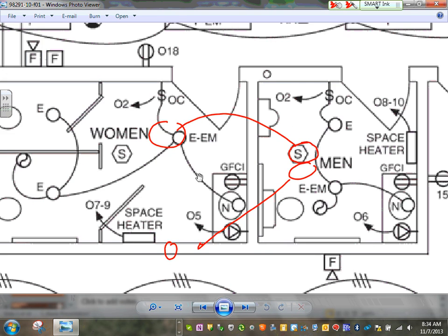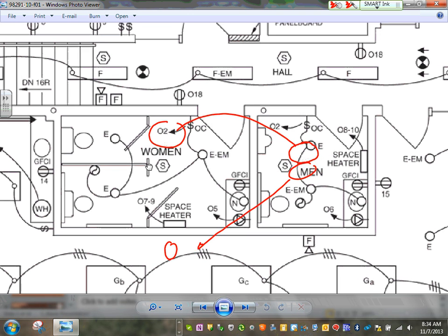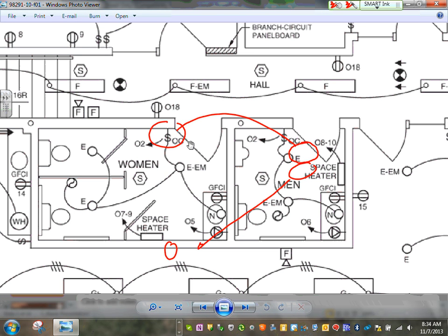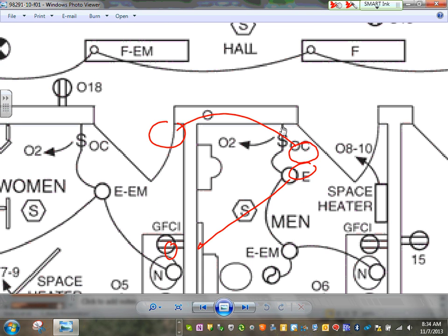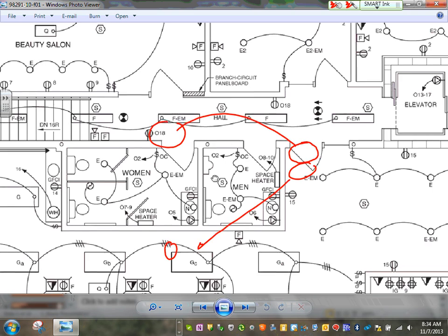If you guys go to the bathrooms, in the bathrooms they have a couple of emergency E-light fixtures, with an emergency fixture right in the bathroom. Can you guys see that little emergency fixture with an occupancy sensor in the bathroom? Can you guys see that, how they did? This is exactly what you guys are going to be doing with your friend Chad. You will have an occupancy sensor, except it's not in the wall. Adam, it is going to be right in the ceiling. So they did the same thing. They have one receptacle for general purpose and the other receptacle for, I think, a water heater here, if I remember right. There's a space heater also here. So that's what they did for these bathrooms.